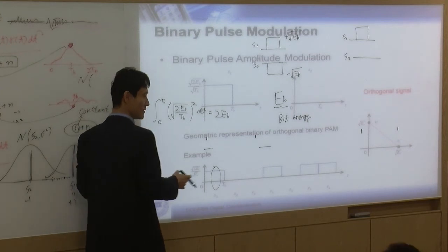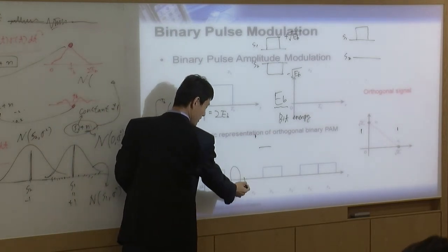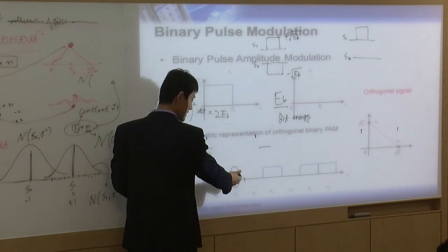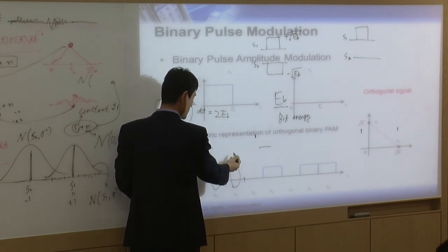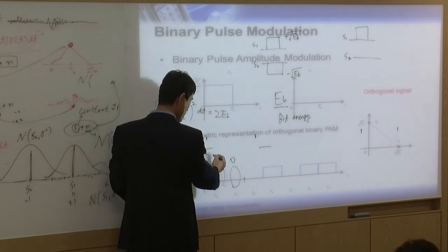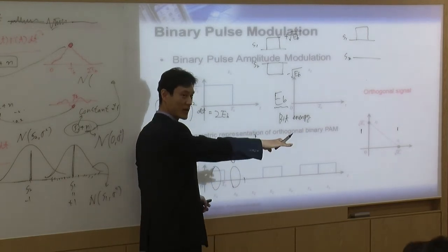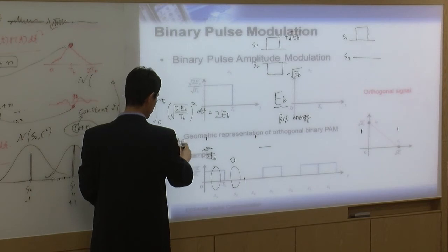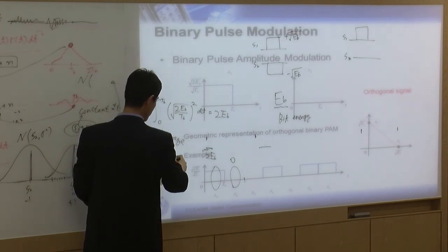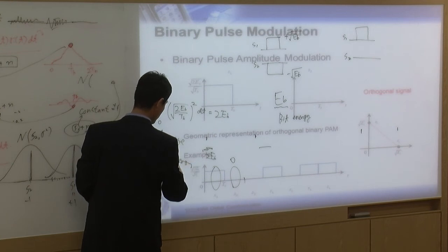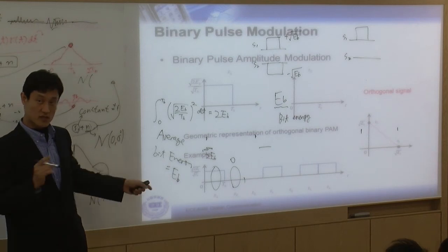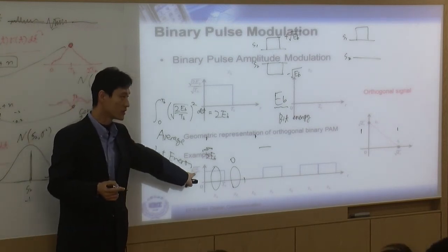Nothing is wrong. Because for the next symbol, the bit energy is 0. In this case, the bit energy is 0, right? So therefore, for the first symbol here, you have to have 2 EB. That way, when you take an average over the whole time, the average bit energy is EB, E sub B. So this is why we have root 2 here.